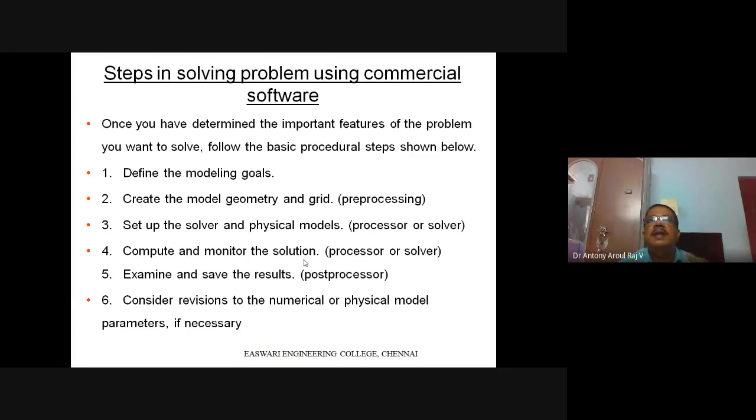So that means in any CFD analysis, first we have to model the domain. Model the domain means we have to draw the domain, using your preprocessor, which can be any solver. Here you can see in Design Builder, I can do it with the Design Builder preprocessor itself. I have to draw the fluid, and after that I have to mesh it. So what is meshing? It is the process of dividing the domain into a number of regular shaped subdomains.